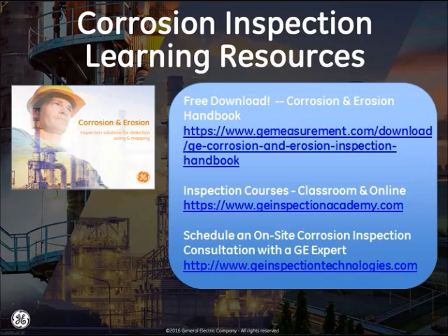Yeah, this is Dave. Maybe I can follow on Johnny's comments. There are specific ultrasonic transducers and setups which allow you to measure oxide scale. Johnny talked about a screening tool with radiography, and then if it turns out to be a concern, remove the insulation and do an ultrasonic thickness measurement. That is definitely the way to go.